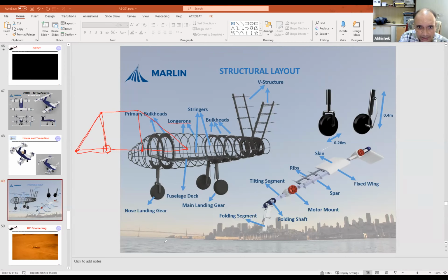Maybe yes. Some of these techniques, RC models, you don't make truss so much. But the point I was trying to make is that this is a more conventional truss. 3D trusses would have this kind of triangular cross section, for example, and this whole thing will be extruded. It's sort of like a small, elongated pyramid. And inside this, you will have these members connecting like this to make it strong and rigid. So there will be these interlinked members everywhere. This is a sort of 3D truss.